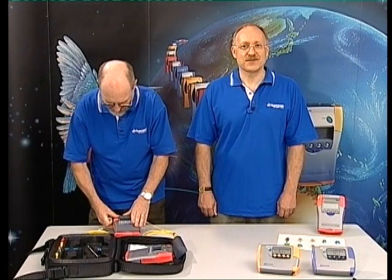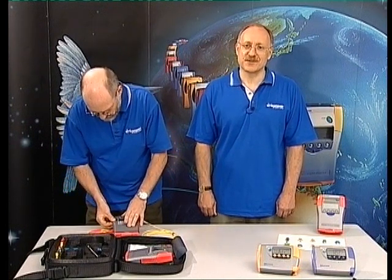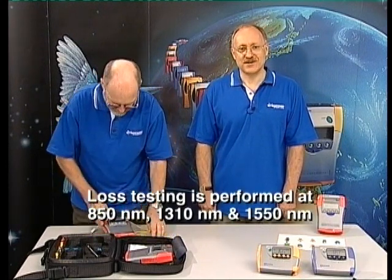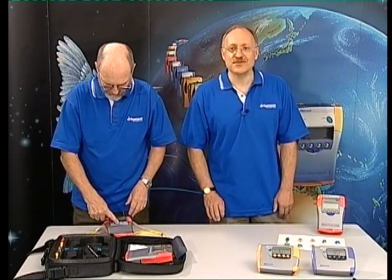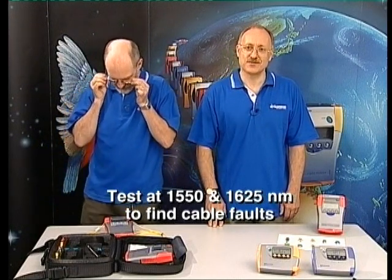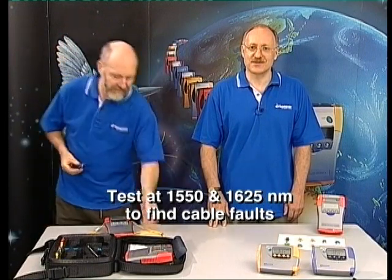Optical cable loss is wavelength dependent, so testing is performed at current and expected operating wavelengths, such as 850 nanometers, 1310 nanometers and 1550 nanometers. Testing may also be performed at long wavelengths, such as 1550 nanometers or 1625 nanometers, to help identify cable installation faults.